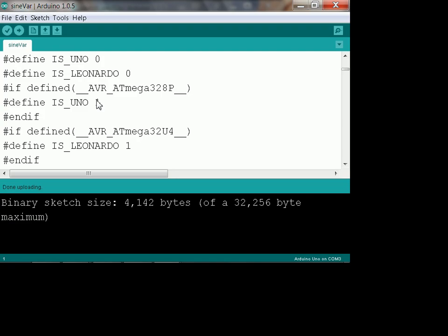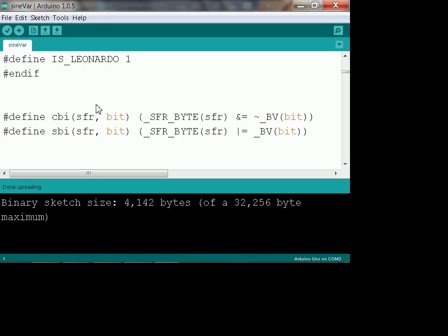So if you're going to build a PWM DAC, you've got to deal with the fact that adjusting the duty cycle on that DAC is very CPU specific, because each timer and its register locations are different depending upon which model of Arduino you're in. And that's kind of a pain, and it makes your code very non-portable. And that's a problem.